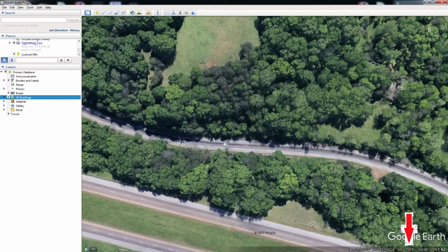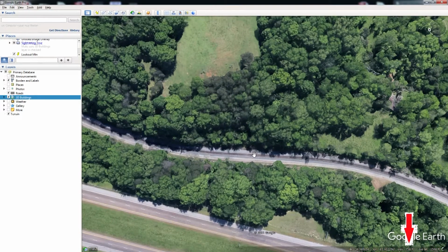In between the two, where this radius ends, there's a short straight, a short tangent, and then the next radius begins. You don't usually have a reverse curve that goes from curve to curve without some sort of small straight, even the smallest straight section, to allow the cars and the elevation to change. There needs to be a certain amount of straight in there in real life in order for the forces within the train to not be excessive that might cause it to turn over. So like you're coming through this curve with some super elevation, then it would go to flat in the tangent, and then the super elevation would pick back up as you enter this radius.